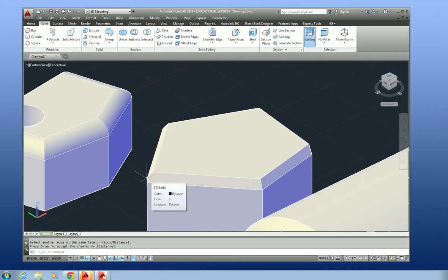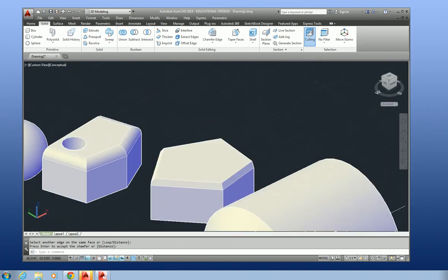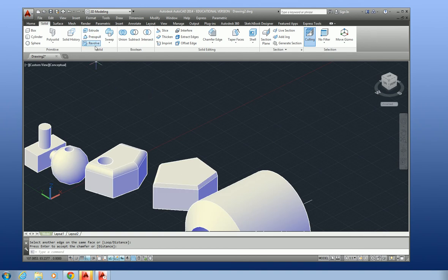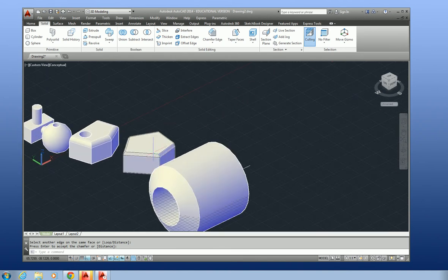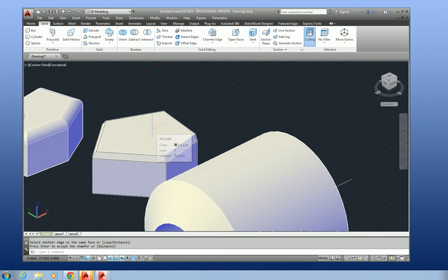Okay, so we've covered just about everything. Let's see, revolves, primitives. We won't cover exactly everything. Oh yeah, here's a neat one that we might use in chapter 10, but I'll get more into chapter 10 because that one's a tricky one. Is the shell. The shell command can be very aggravating. I've selected shell, left mouse button, click my object. Right now it's asking you what face to remove. Here's where the problem is. That face does not always remove. So I'm clicking the face. Okay, and it says it's removed.